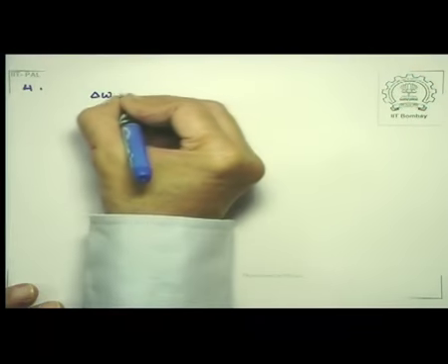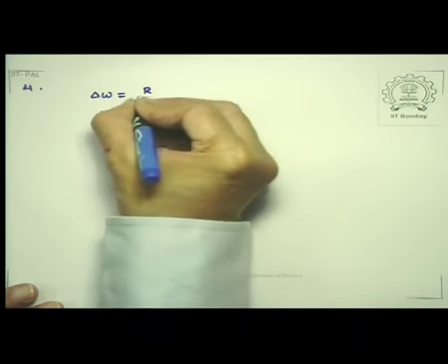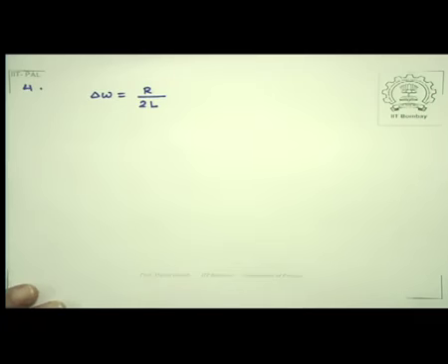So therefore, a smaller bandwidth means a sharper resonance. The curve becomes sharper, the width becomes smaller if the bandwidth is smaller. Now we calculated and found that delta omega is equal to R by 2L, so that the full width at half maximum is simply R by L.